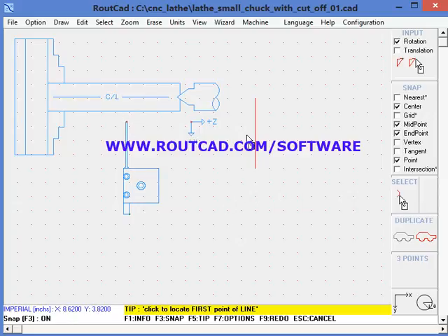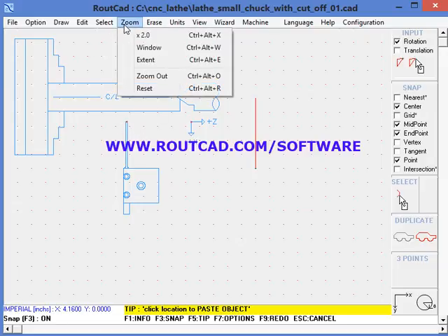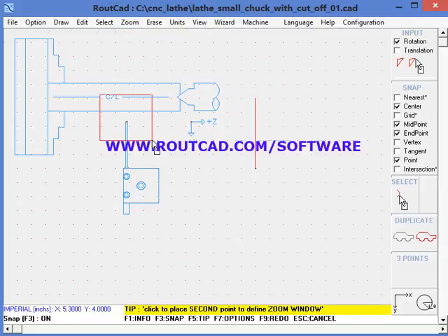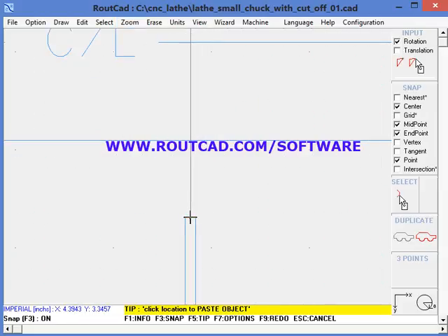We want to make the motion of cutting that cylindrical workpiece. Easy. Let's move that line to that point. We're going to go to Copy, and we're going to select that line first. Duplicate is not checked. This is good. We're going to select the end point of the line, and we're going to move that line. And what we want to do now is to drop that line at that end point. So let's zoom window, and we zoom that area. Now we can continue our work, so we can drop that line right over there. Because we had snap to point, it went to the point.